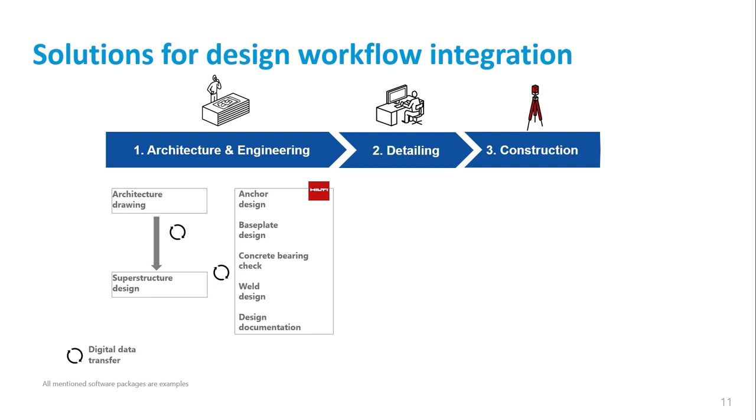What we can do, and later on I will show you a video, is that our new software is able to take loads from SAP, you mentioned SAP 2000 and ETABS, right? It is able to connect with them and grab data in the background. You can select which load combinations and which node you want, and then in a digital way transfer the 100 load combinations over to PROFIS, and with one button PROFIS will calculate all 100 in probably less than a second, and give you the one that is worst case for you.